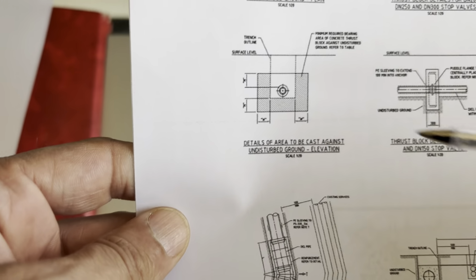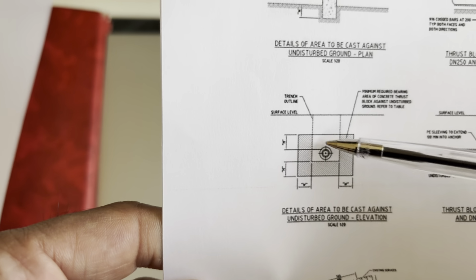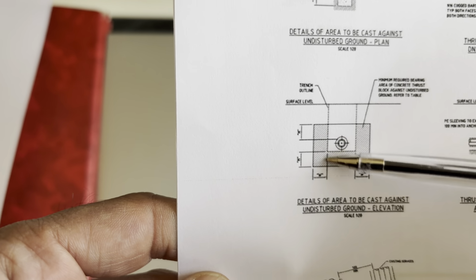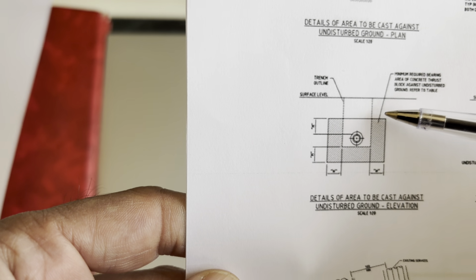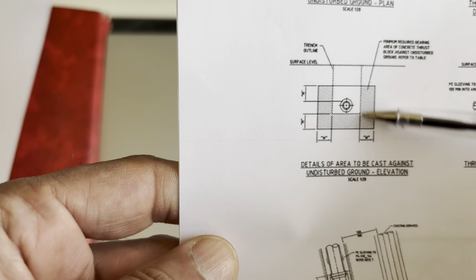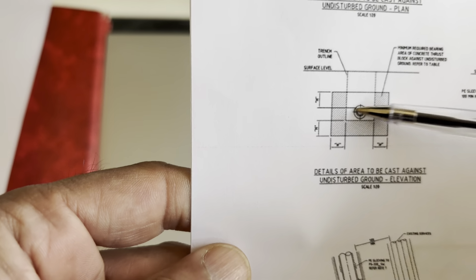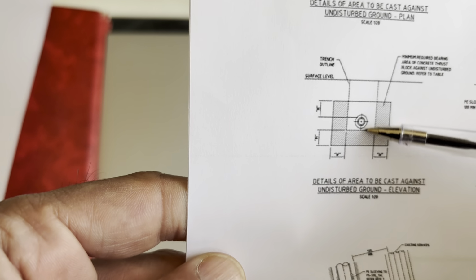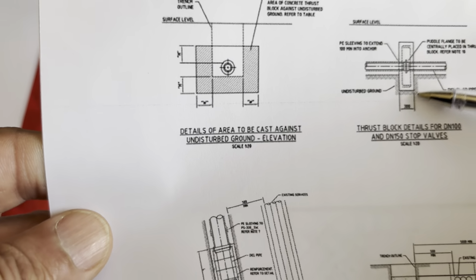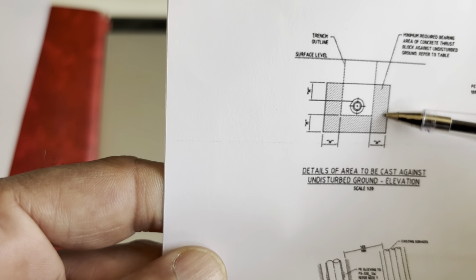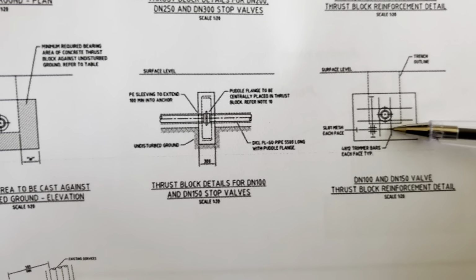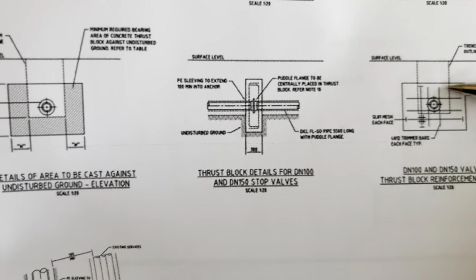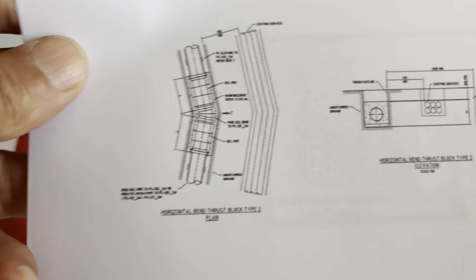And depending on the geometry of the site, we may have this type of system. It can be the soil here and the anchor block, the concrete part here, and it should be connected or anchored to the system here. And definitely in these situations, in most cases, we need to have reinforcement for bending and shear capacity of this concrete block.